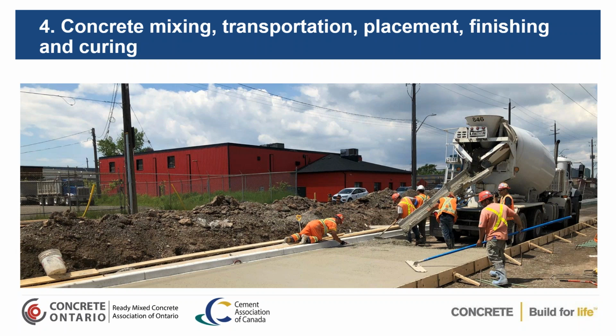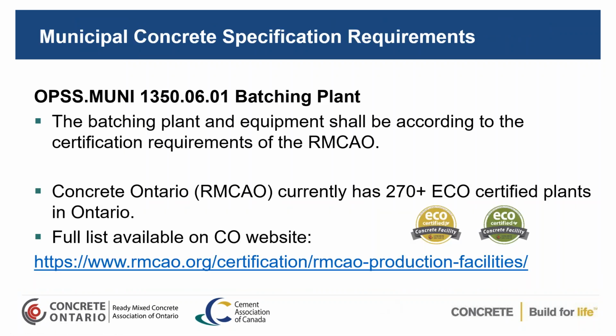So here, we'll now go to the transportation of the material to the job site. You'll see in this case it's a fixed form paving operation, and they're able to back right up to the job because there's no dowel baskets in this job. Otherwise, they'd be doing side loading. And again, they've got the wooden forms well staked to ensure that they will stay in place.